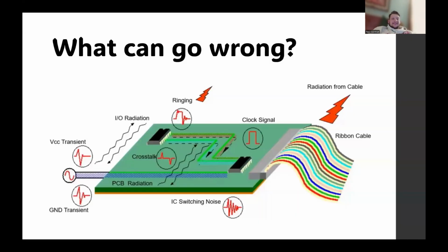Electromagnetics is relevant because signals are not confined to the copper. They exist as electromagnetic waves traveling through the dielectric material between the traces and its return path. Whenever we change currents or voltages quickly, we generate electric and magnetic fields. And if those fields leak out, they couple into other circuits, or they have the chance of reflecting to other objects due to impedance mismatching. And the result of that is called EMI, or electromagnetic interference.